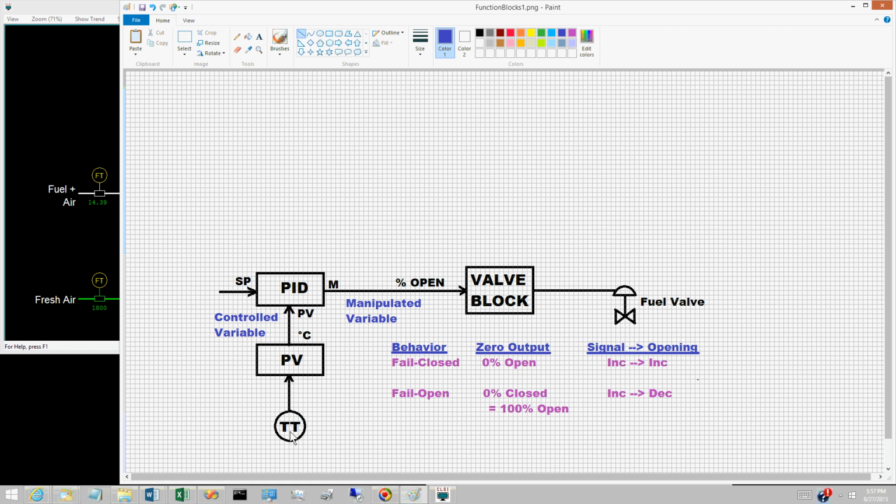In process applications, the future is inputs in the form of digital values from smart transmitters. However, 4 to 20 milliamp inputs remain common, and other types are also encountered. Digital controls begin by converting each input to engineering units. To perform this conversion, a PV block must be configured for each input. The PV block in the diagram is for the hot air temperature. The input is the signal from the transmitter. The output is the temperature in degrees Celsius.